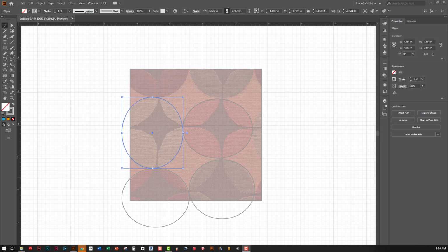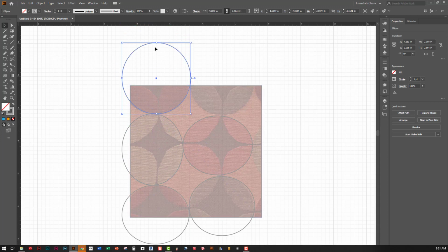There are a few handy-dandy tricks that I can tell you about, one of which is if you're drawing with your various objects and you just want to make a copy of one, select it, but then hold down the Alt key, and as your mouse goes over the edge of the path, you can click and drag, and you'll make a copy of that object, which is totally independent, and you can continue to draw.